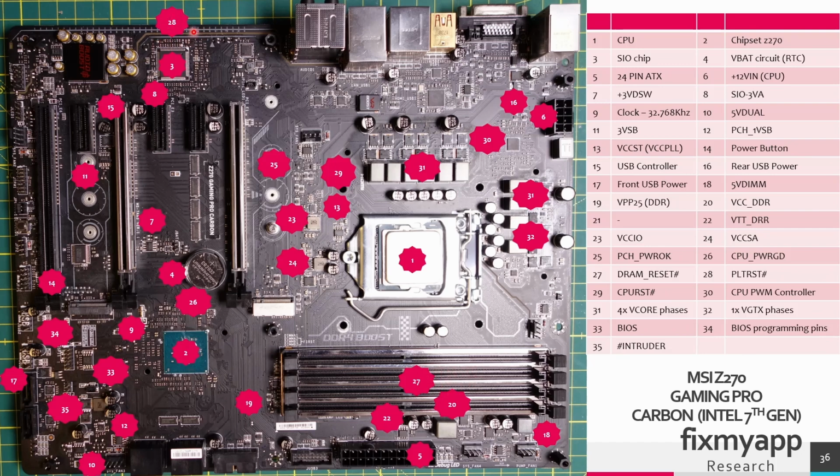In this area near the Super I/O, there is a signal called platform reset active low. The hash symbol indicates that it is an active low signal, meaning the reset is triggered when the signal is pulled low to ground. So every signal that has a hash is active low, meaning it is active when it's pulled to ground.